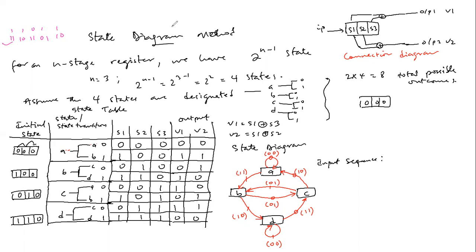So let us go on. So in our case, we have the input sequence 1, 1, 0, 1, 1. So now the output sequence, or the decoded sequence in this case. Now, when 1 is transmitted, coming from state A, if it were to be a 0, then we'll move this way, but now it is a 1, so we have to move this way. So it means from state A, we are moving this way, right? Because 1 is emitted.